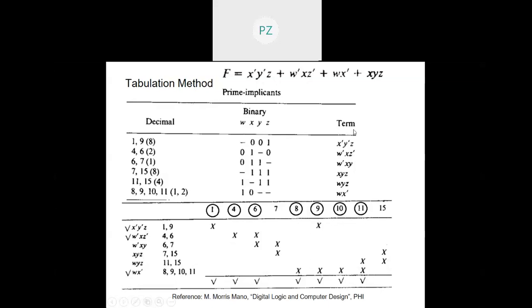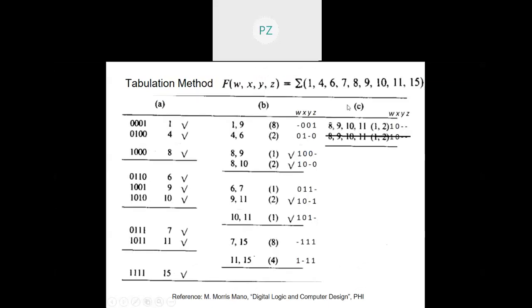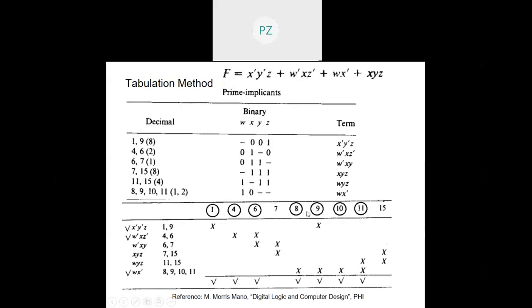Before that, treat don't care as very much a part of the function itself. And in the last step, don't include the don't care condition, and then identify essential prime implicants, write down essential prime implicants, and then to it you add the minimum number of min terms or the product terms or the sum terms, as the case may be, in order to complete the function. So that will be the difference when you have the don't care condition.